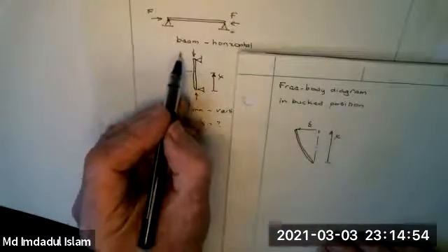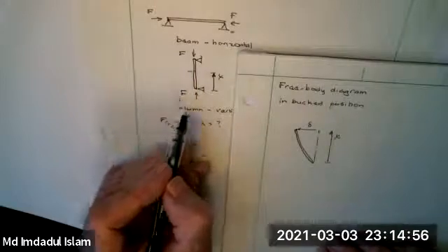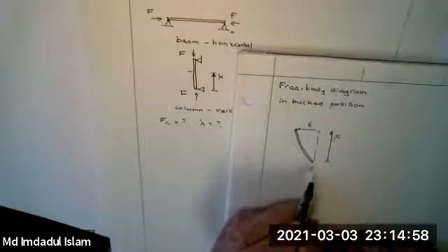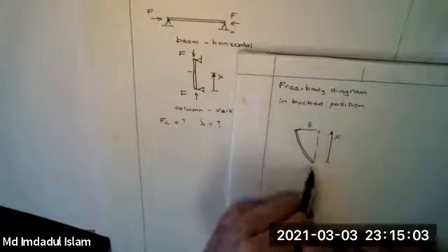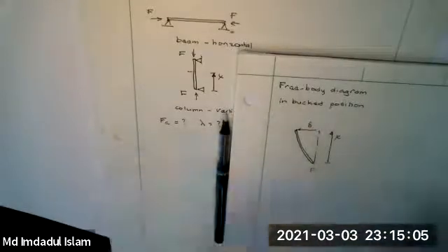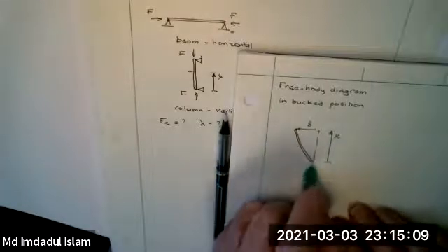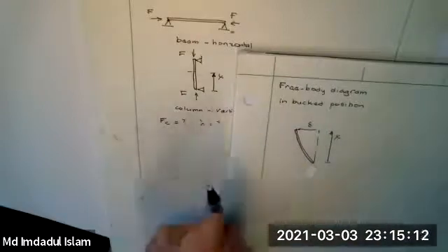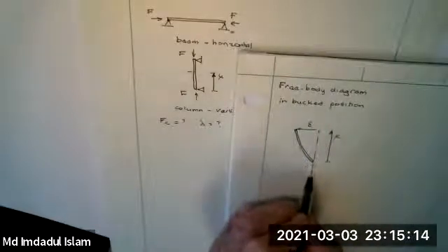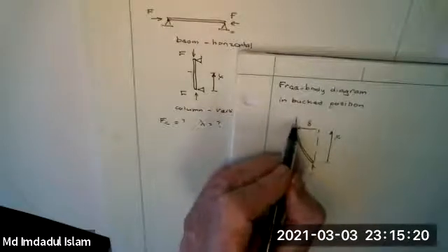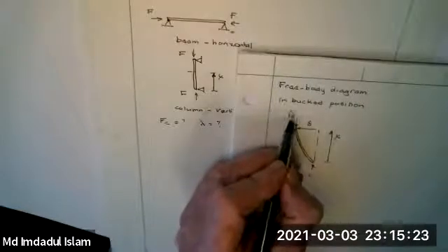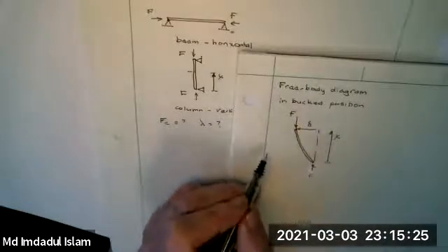I put the force F for both of these, so the reaction here is F. There's no moment here. If I resolve vertically, let me put the arrow in there, it'll be clearer. If I resolve vertically, I'll have an equal opposite force here, F, but I'll have a bending moment.